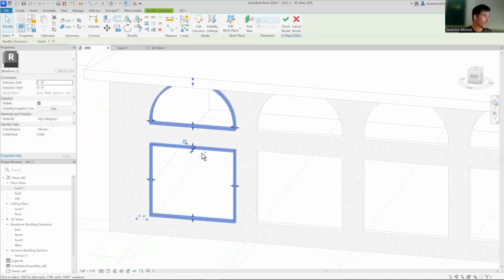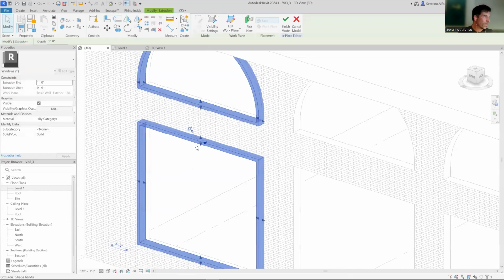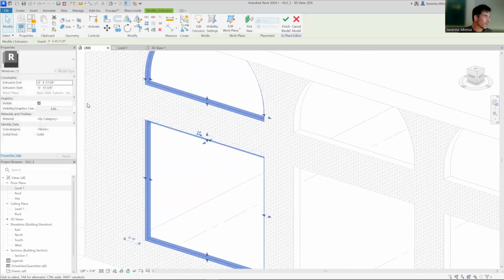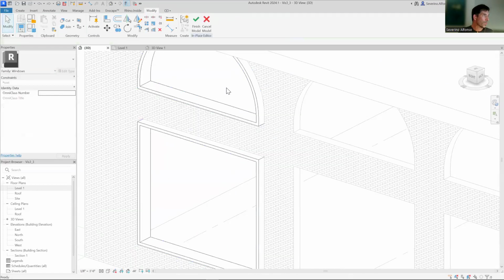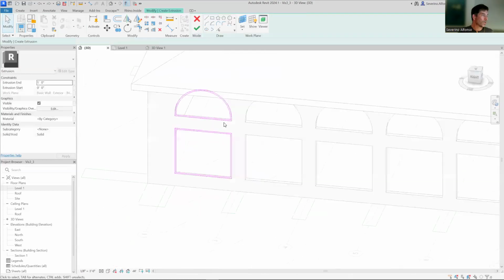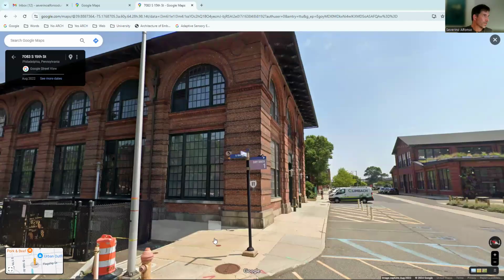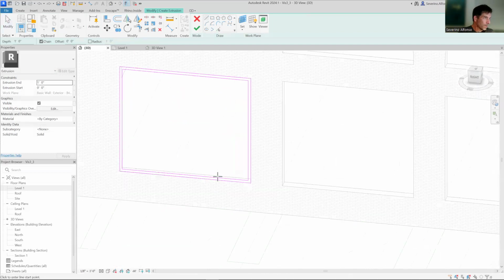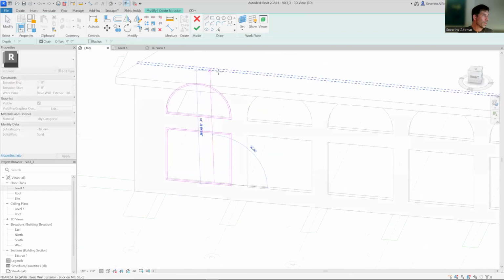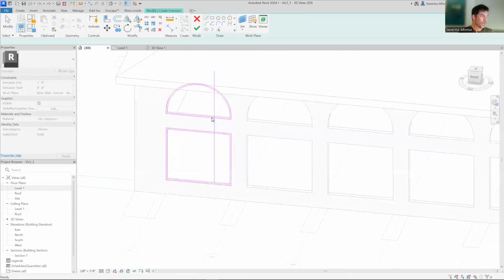Notice how we can see the beginning point of a mullion in a way, and stir it in different ways. We could do that numerically. But I'm going to go back and do much more detail. It's two vertical lines that are not in the middle. So I'm going to do a line here. I'm going to place it, and notice how I can see the dimensions, maybe at 4 feet going up. Make sure it's vertical.